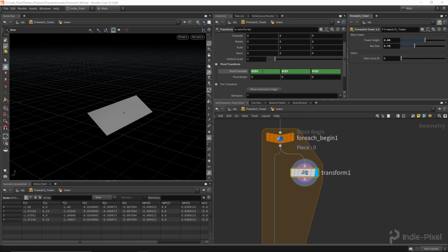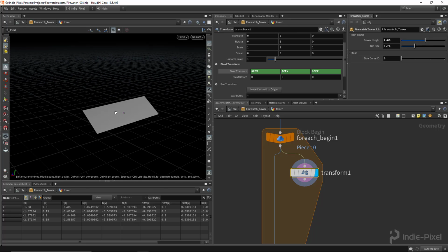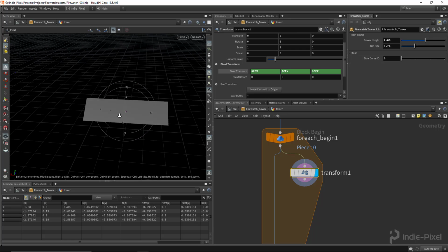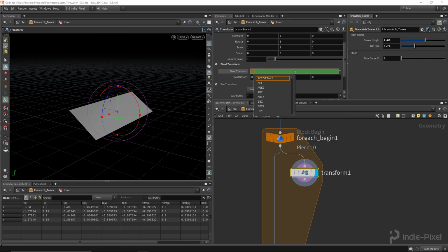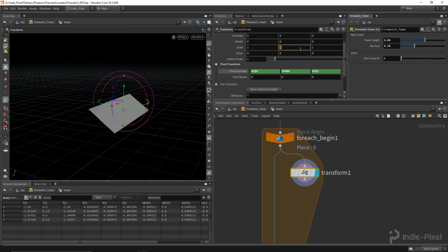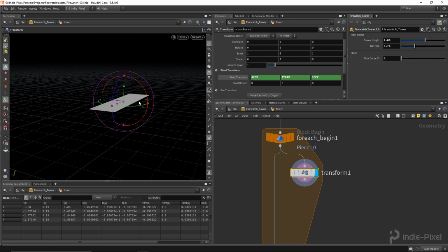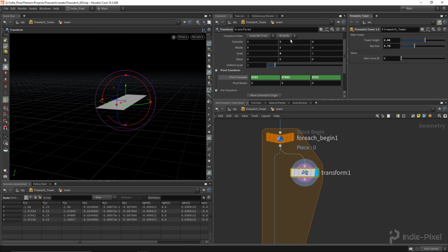All right, that stands for the centroid of this particular piece of geometry. Okay, so let's hit enter. You can see now we actually have it at the center. And I actually think I'm going to keep it there. If you wanted to do the highest point, since I was talking about that earlier, you just do $Y max. And now you're at the highest point. So now you can hit 0 on the scale, and it would go up to the highest point, right?